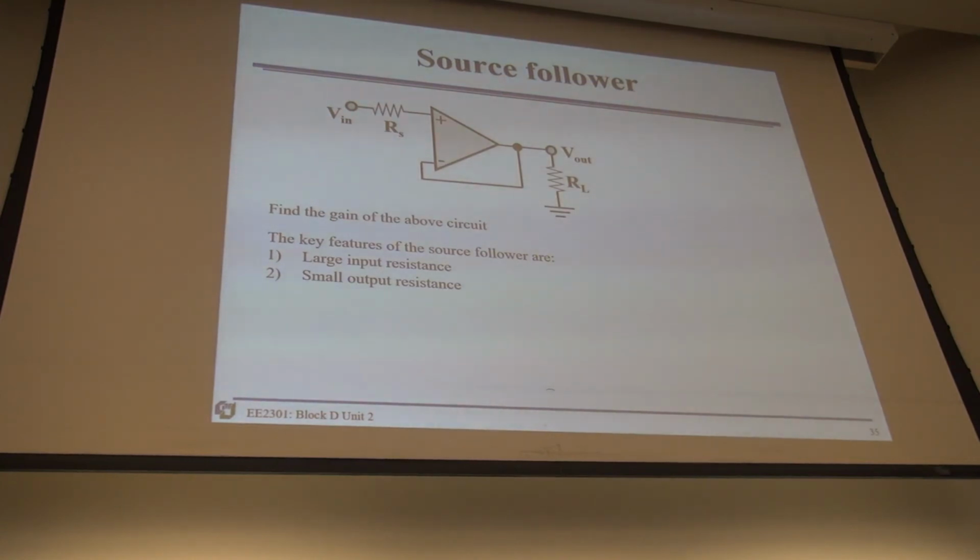So that's a very important buffer for you to condition your original RS. Condition, you use a conditioner, right? So RS, previously you made it big, and now you want it to be small. What do you do? Add an op amp as a follower.